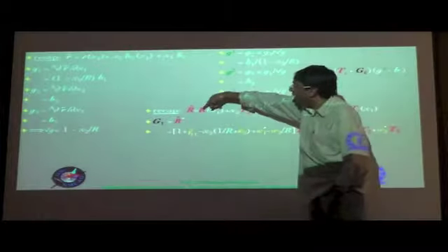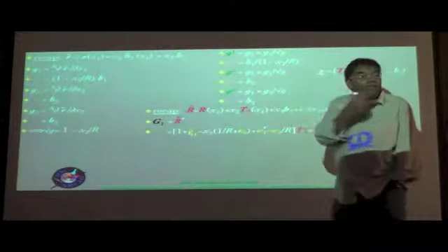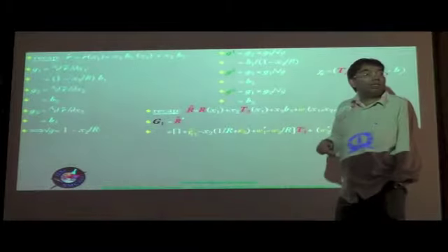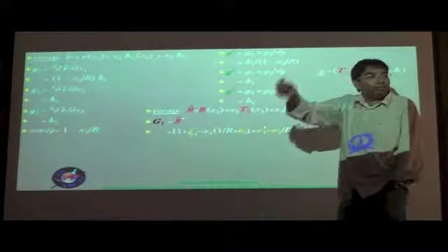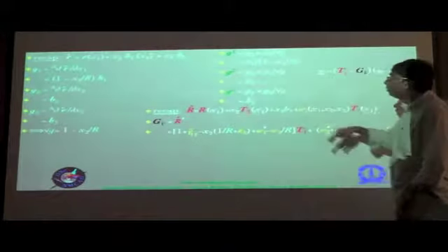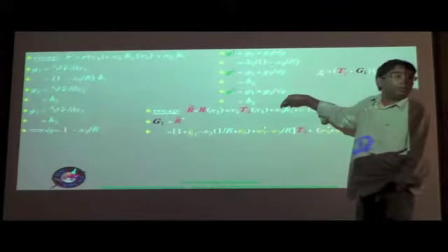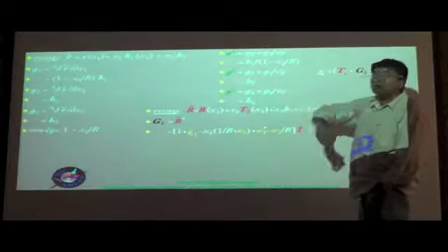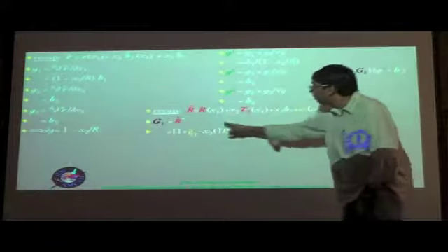So G1 is nothing but your r hat prime, which is given by this expression, which is quite easy to see once again. You have to only look at terms which are dependent on x1 over here. Remember that we already talked about the big T primes as well in terms of the initial radius of curvature r and the kappa 3 bar, that expression we had in one of the earlier slides. So we are basically utilizing that in determining T2 prime. Of course, T3 prime is equal to 0 because T3 is equal to small b3 and doesn't vary along x1. So that will be left out. So only T2 prime will basically contribute over there. This term in fact doesn't contribute to this expression at all.